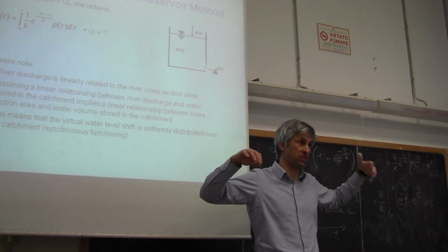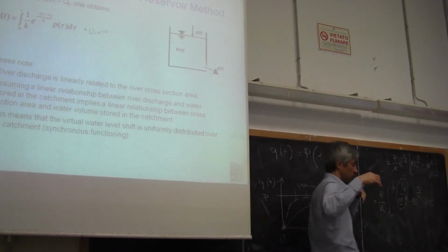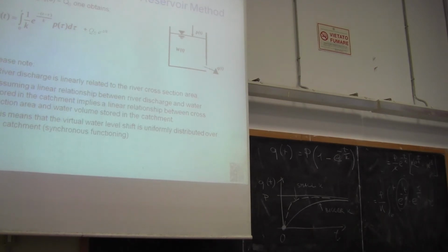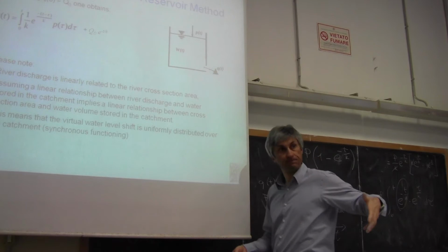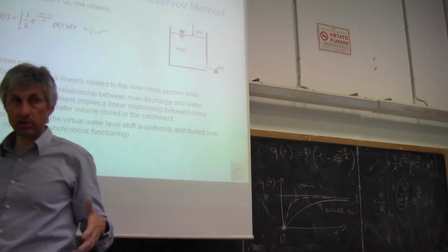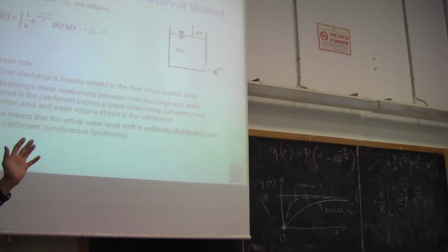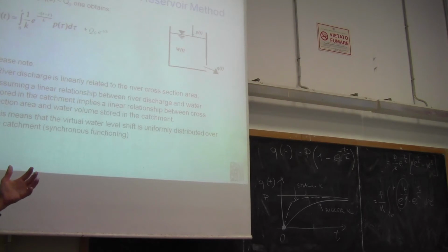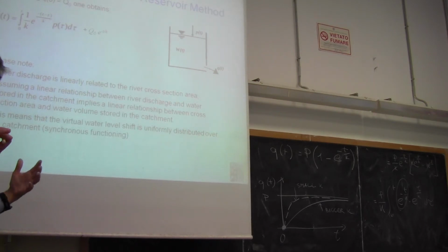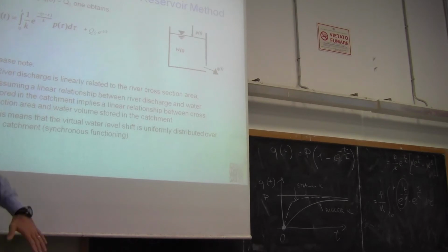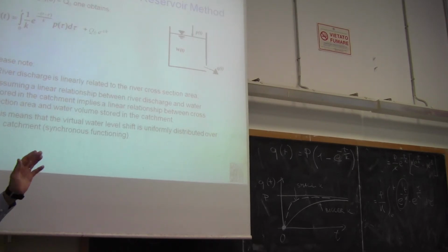If you have a catchment that is permeable, that gets a lot of infiltration and has a lot of storage, then it's less dangerous, because after a rainfall it takes a long time before delivering the volume of water that rained over it. You always have to be concerned, in terms of flood risk, about catchments with a reduced storage. And the reduced storage is given by the catchment being impervious, which means not permeable, or being very steep, because the two things are strictly related.